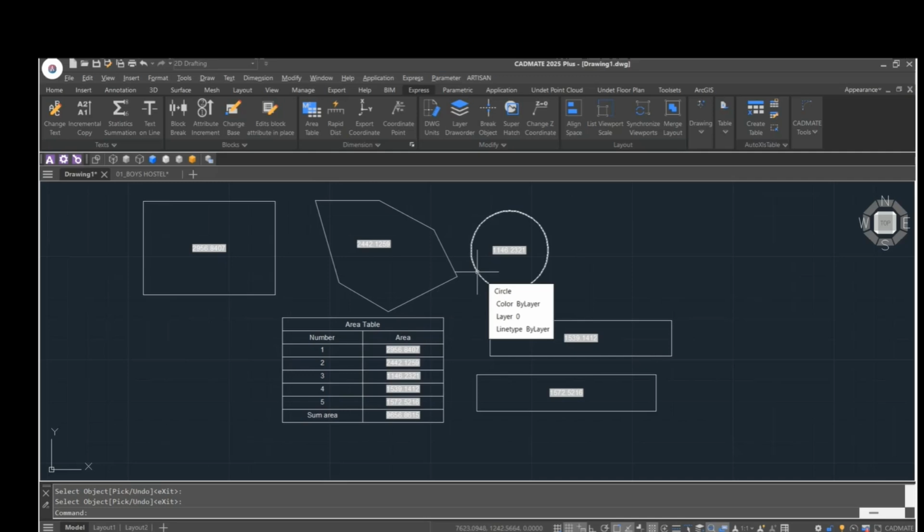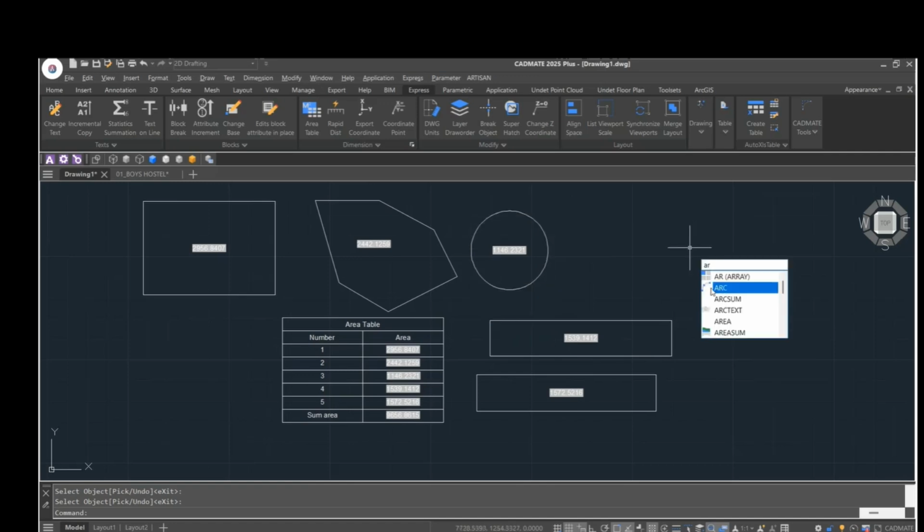So this feature is not there as of now in BricsCAD, right, Deepak? No, so in BricsCAD, when we select multiple areas, it will give us the combined area, but this table feature is not there. The combined area we get in BricsCAD by default. It's there in AutoCAD as well, the general area command. So once you select, you can start selecting multiple items. It will give you the area directly.